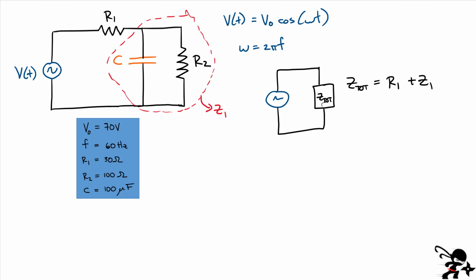What you have to remember is that the reactance of the capacitance is 1 over omega c. That's the definition. And if you wanted to calculate the impedance of that branch with the capacitor, you have to introduce this complex variable over here, and that's it. So now we have a value for the impedance of the branch with the capacitor.